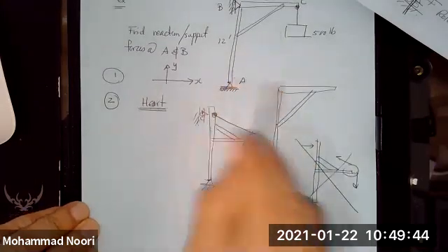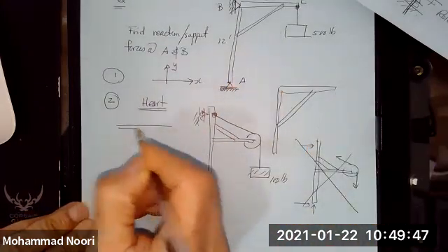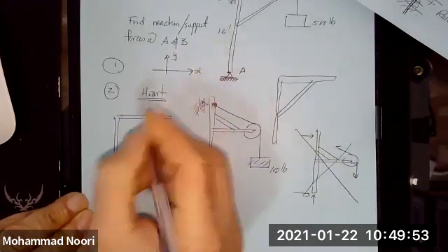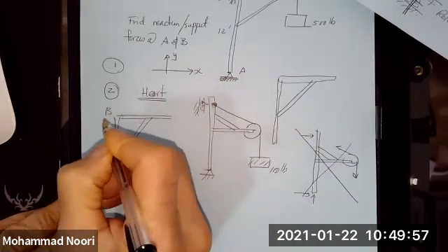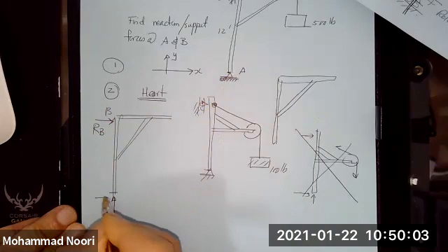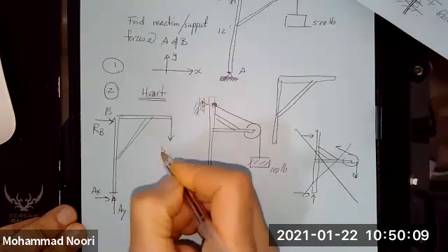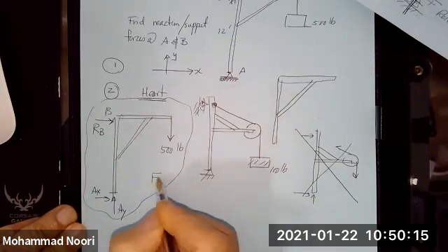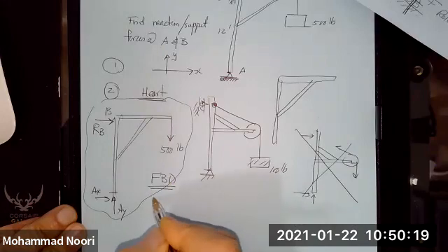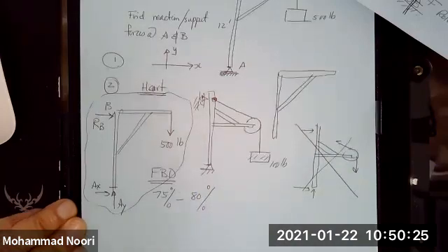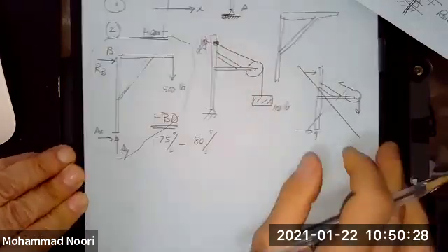So getting back to this, if I draw the free body diagram, this is going to be the free body diagram. At least that's what I assume as far as the direction. At point B, I do assume that you have a force like this. At point A is a pin, so that represents two unknown forces. And then here you have the applied load. So this is the free body diagram, which, as I said, is 75% to 80% of understanding statics. Okay.